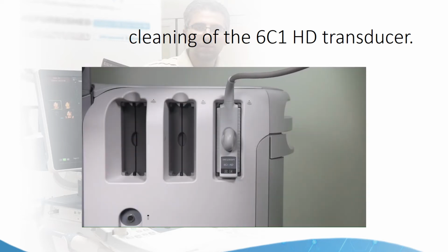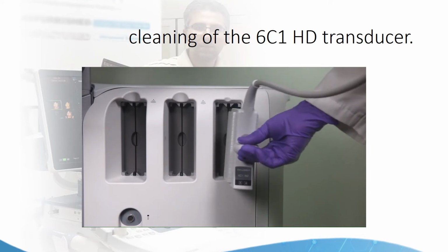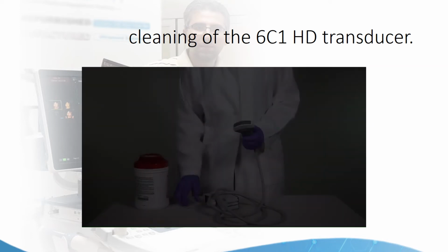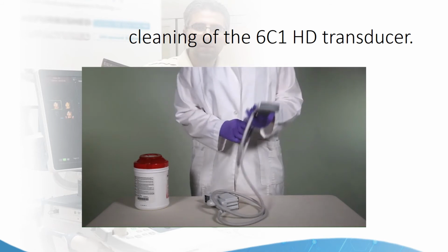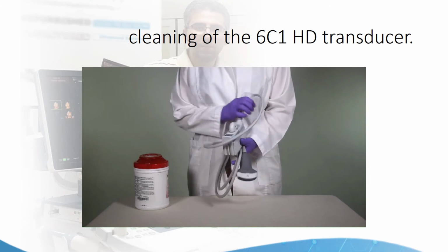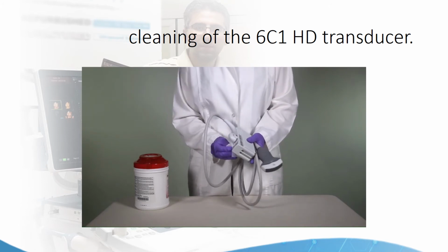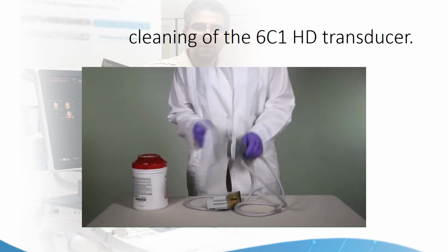To clean a transducer used externally on intact skin, begin by disconnecting the transducer from the ultrasound system. Dampen a clean gauze pad with water and wipe the transducer, cable, and connector to remove gel or particles. Use a compatible disinfectant wipe to complete cleaning.